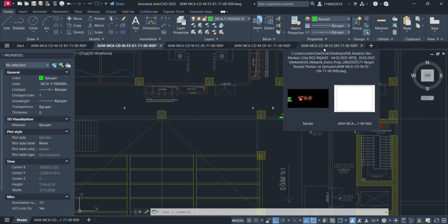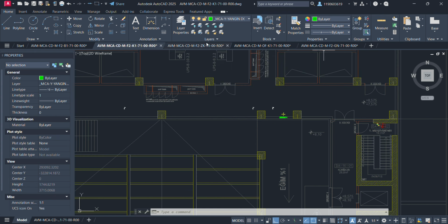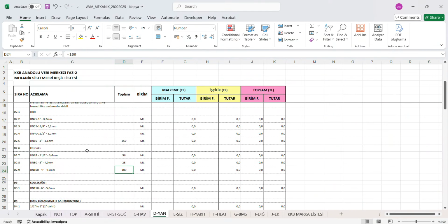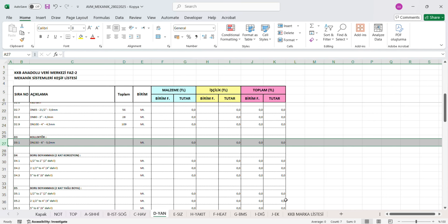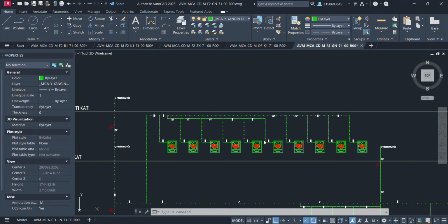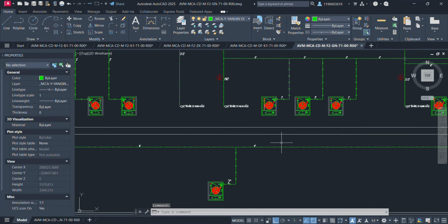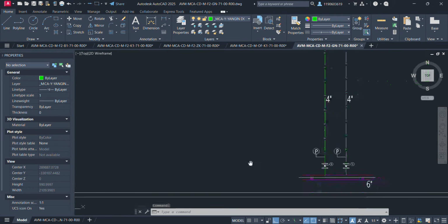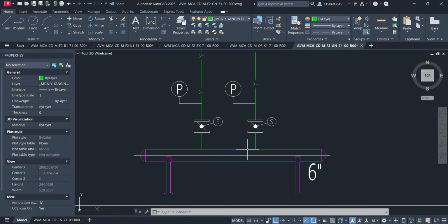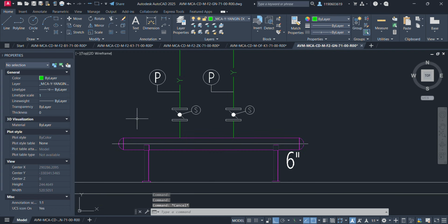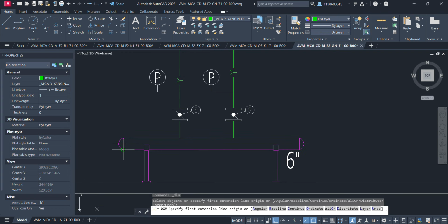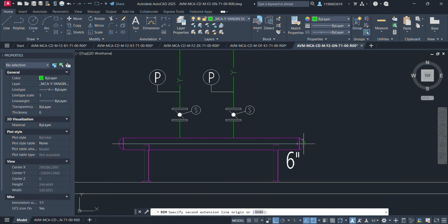They are installed on rooftops or high parts of buildings and are filled with water to provide continuous water pressure in case of a fire. Special pumps are used to pump water from the tank to the pipes leading to the sprinklers or hoses. Ground tanks. These tanks are installed in the ground or in the lower floors of buildings. They are often used in large areas or industrial buildings. These tanks generally have larger storage capacities and require powerful pumps to deliver large volumes of water quickly.